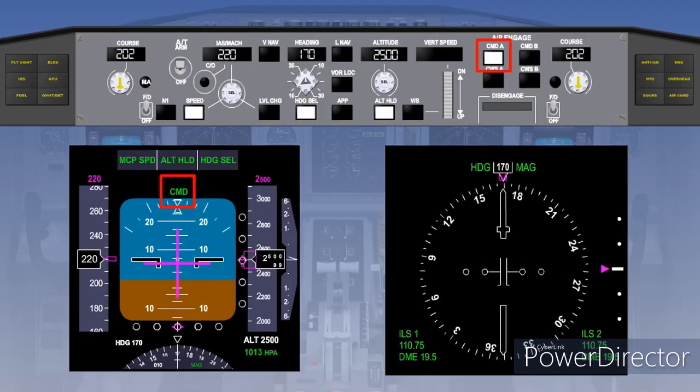During the approach phase of a flight, the crew will normally be under direct control of air traffic control and be provided with radar vectors and descent heights to intercept the final approach course. The aeroplane would normally be set up under the control of a single autopilot, with the auto throttle controlling the mode control panel indicated airspeed. The crew will select the flaps and gear as appropriate to the aircraft during the approach. The autopilot will not select flaps or gear.